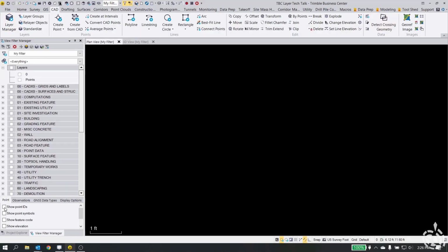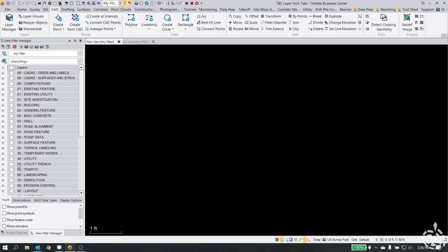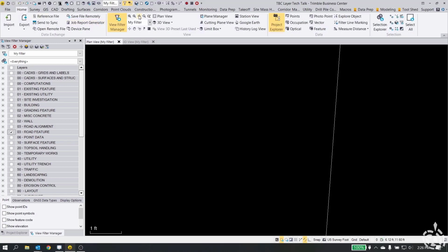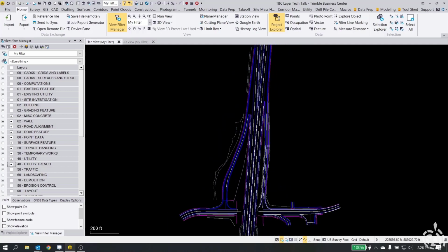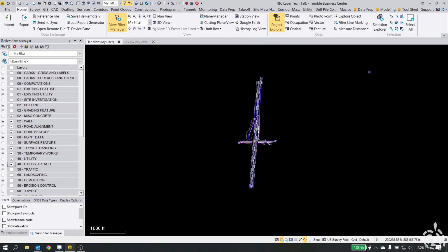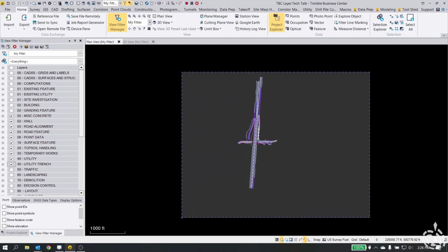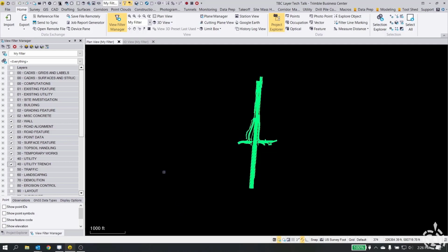Now what I'm going to do is turn on my road features. Let me zoom extents here. Turn on my groups, some surface. I don't remember what I all have in here, but I've got everything on. The other thing you might have to do is, sometimes when these come in from CAD files or DGN files, they might come in with the color not set to by layer.